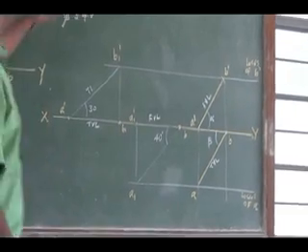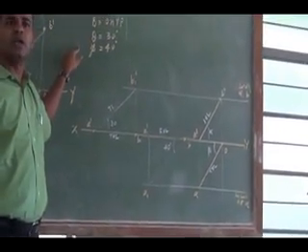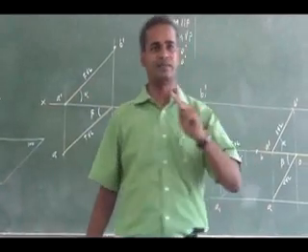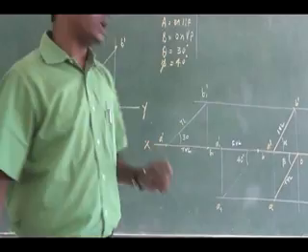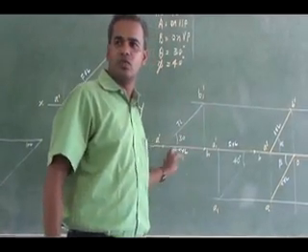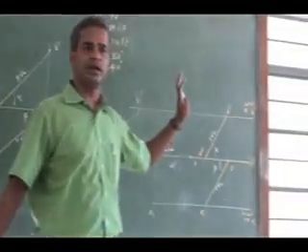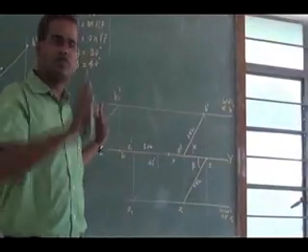This is how, for this kind of problem on lines where one end is on HP and one end is on VP, you have to proceed in 3 steps. You cannot draw it in the same place. If you draw it, you will get confused. We will try to draw it in 3 steps. Is it clear? Similar to the first problem.